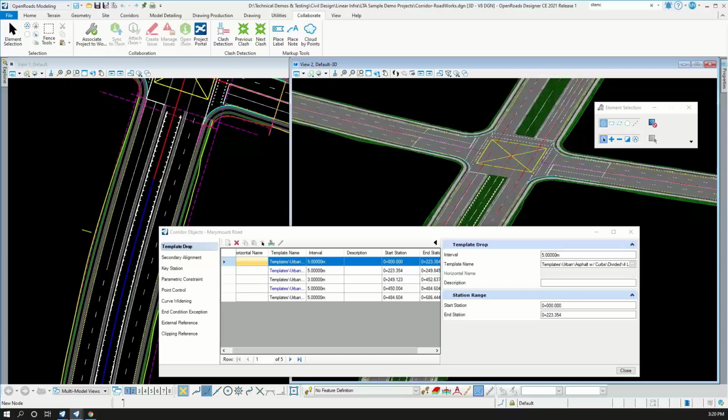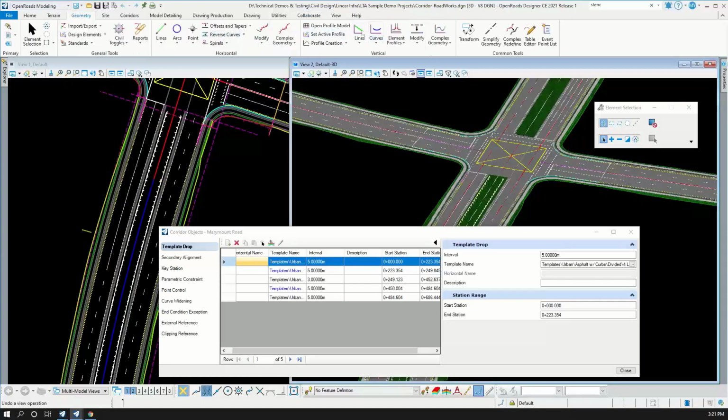Let's move on. Next question is, can the center line median alignment be draped to the surface pavement? There are tools in the vertical geometry tools that would allow you that, maybe profile from surface or quick profile from surface. So all you need to do is lay out your geometry and then profile it according to the surface, or the terrain, or even the corridor. This tool here. Okay, thanks for that.